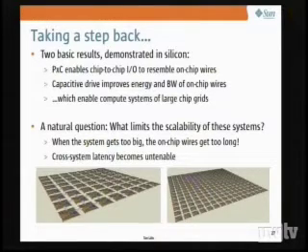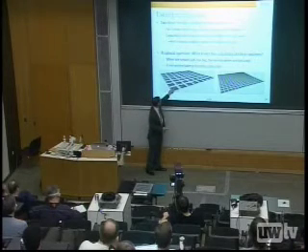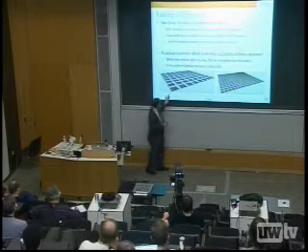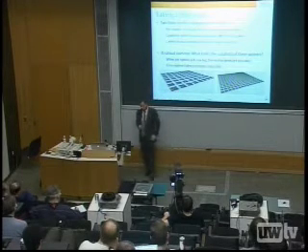What's going to keep me from tiling it out ad nauseum? So here are some cartoons. These are microprocessor pictures. Nothing real about this except that I drew it in a CAD tool that has, in this case, an 8x8 array or a 16x16 array of processors that are tiled with these bridge chips that are face down using proximity communication. And presumably all the on-chip wires have the capacitive drive, so they're efficient.